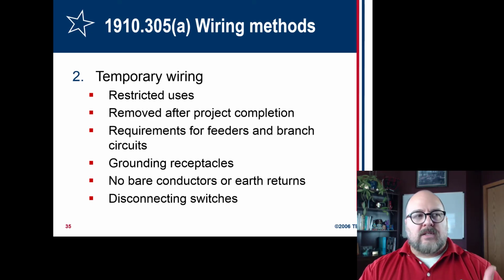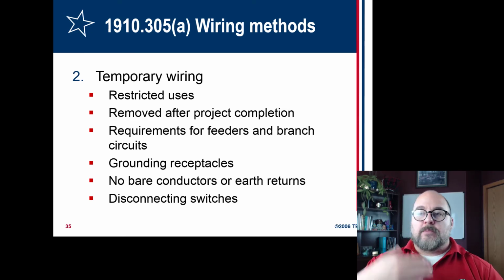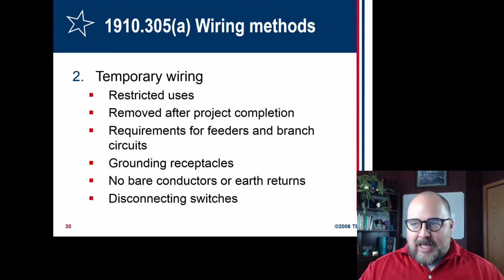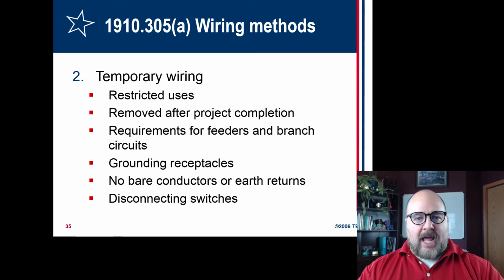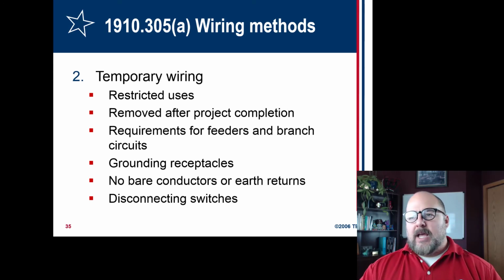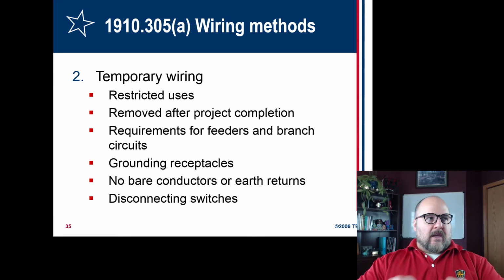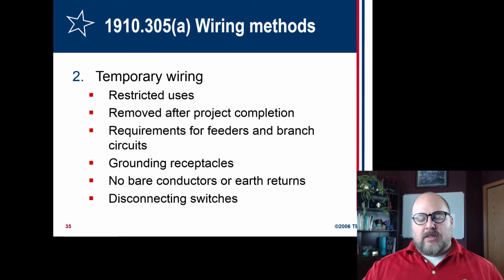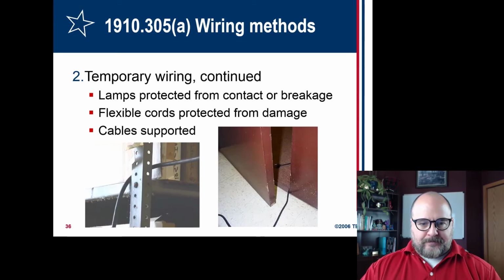And so what they want is they want you to put in permanent wiring, because a permanent electrical system is designed to only function as it's designed to do, whereas an extension cord can be misused and it can be damaged. And you'd rather have the lines behind the wall or secured in a conduit than out in the open.